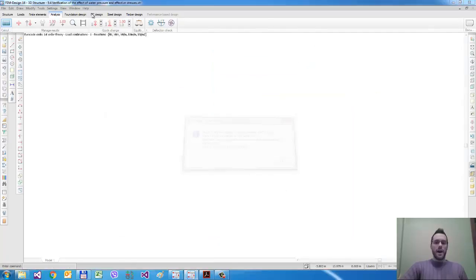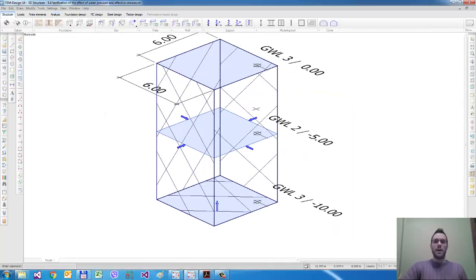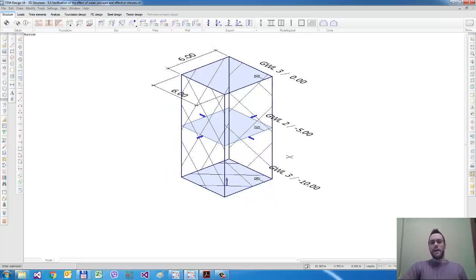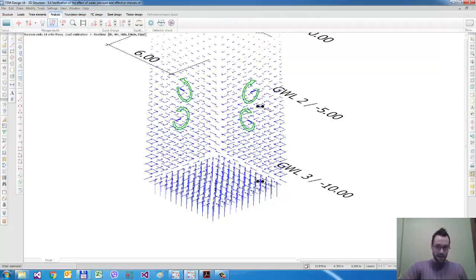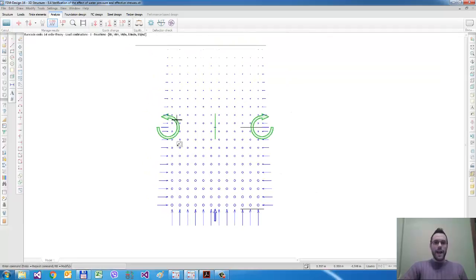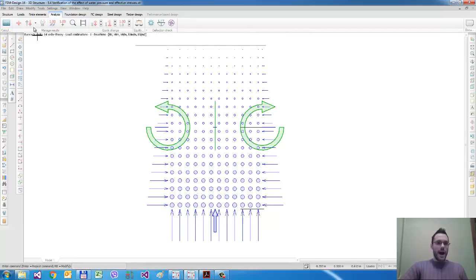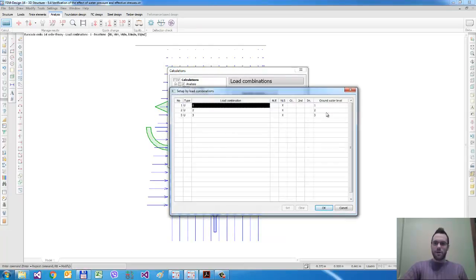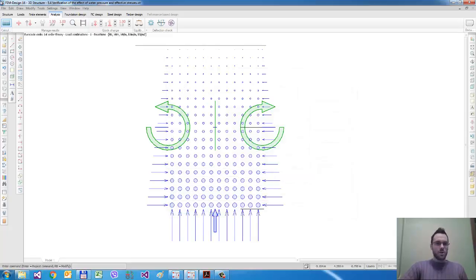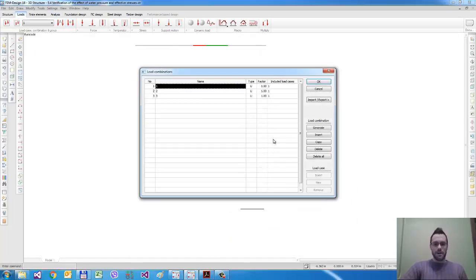So now I have just a soil block and the self weight of the soil, and I applied 3 different groundwater levels: groundwater level 1, 2 and 3. If I check the final results and the reactions at the side walls, I can see that I set different groundwater levels for the different load combinations, but the load combinations contain the same load case, just the self weight of the soil.